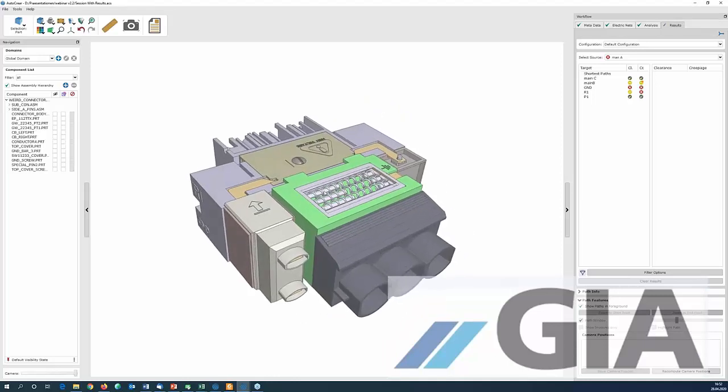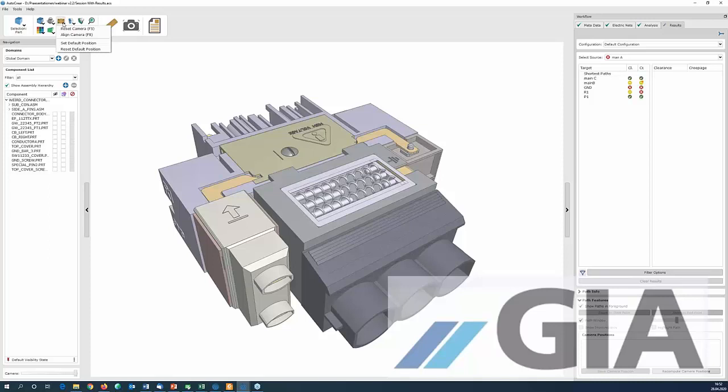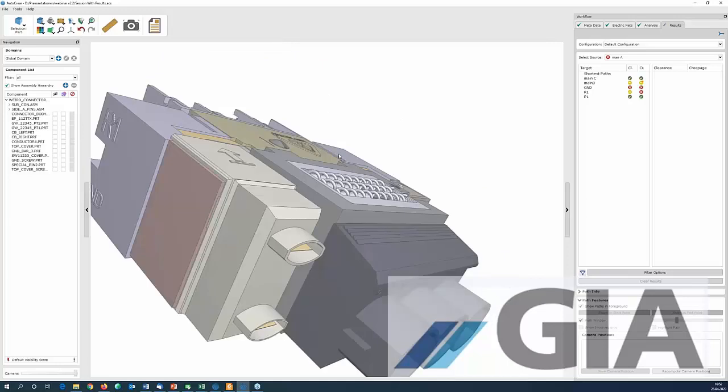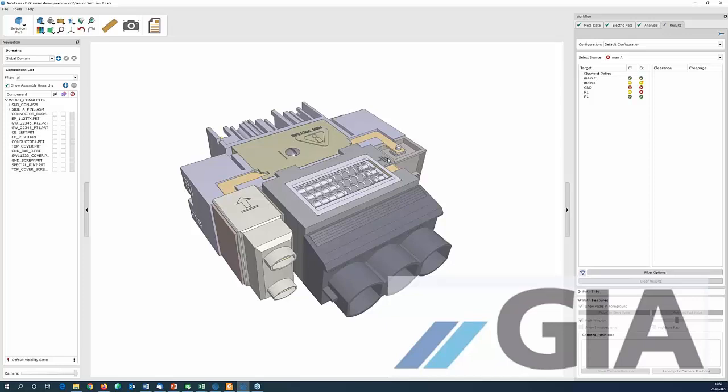This is very simple. You just choose your position, like this one, for example, and then you find the option here in this tool, which originally only contained the reset and the align functions, but now you have here the function set default position. You just click it and now it's set to the current camera. So a reset operation will reset this default view, and also all of the screenshots which are based on this default position are made with this nicer view.